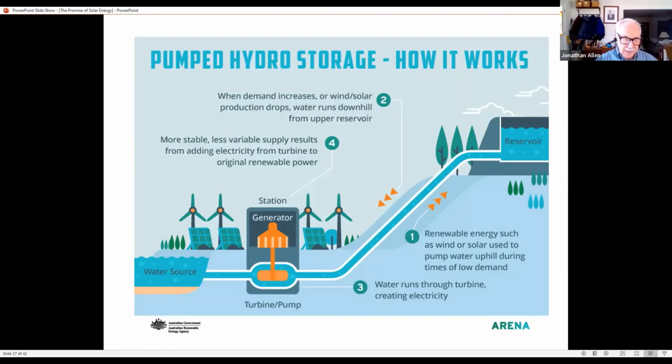There's a new kind of battery that's being developed called the vanadium redox flow battery. It's making its way into the storage business. The electrochemical energy is not stored within the cell, but in external tanks of electrolytes that get pumped through the cells, which convert the chemical energy into electrical, or the reverse when charging. The size of the electrodes in the cells determines the peak power in kilowatts the system can absorb or deliver, while the energy capacity in kilowatt hours is determined by the amount of electrolyte. This allows the designer to adjust the two variables independently, and a typical round-trip efficiency on these is about 78%.